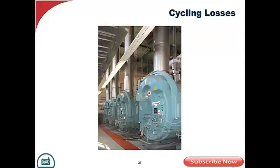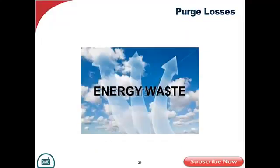Why is that? The pre- and post-purge losses. Every time that boiler goes down, it has to go through a post-purge loss. Post-purge. You're blowing ambient air through that boiler and chilling it down. Then it goes through a pre-purge before ignition. That's another 90 seconds or a minute and a half blowing air through that boiler. You don't want it to do that. You want to keep it online. Because all we're doing is blowing that energy out the stack into the atmosphere, heating the ducts. That's all we're doing. And remember, when we're talking about burning fuel, we're talking about burning dollars, cash.